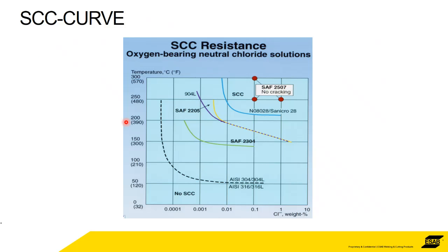In terms of stress corrosion cracking resistance, exactly the same process again for submitting the component to the relevant parameters at temperature, and you come out with a diagram like this, a graph again. So this is done completely empirically, and what this is showing again, so you've got 304, 316 stainless here, can only cope with a chloride weight of less than 0.1%. Anything bigger than that, it will crack, and below 50 degrees. Whereas at the other end of the scale, we've got 2507 super duplex stainless steel. There's no cracking at all, even at elevated temperatures and something up to 1% chlorides.